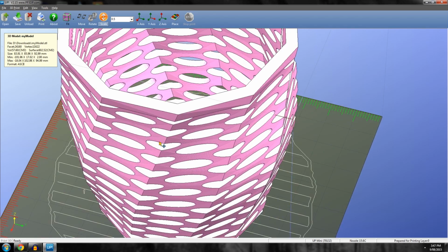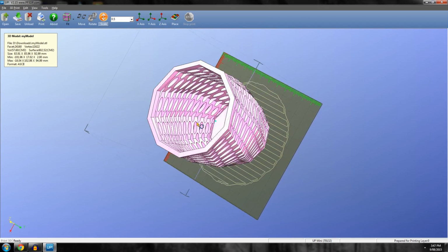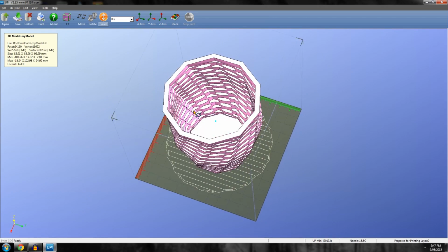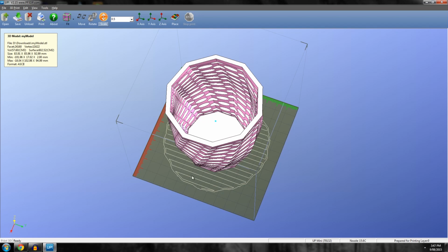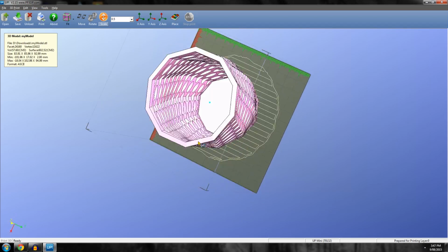And also, worth noting, if you're printing something at 120 millimeters across on an Up Mini, it's probably not going to let you print it because the raft is usually bigger than the part, so the raft might be 125 millimeters, which is outside the bounding box.